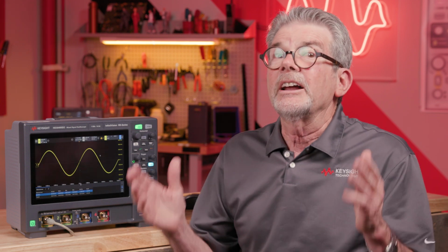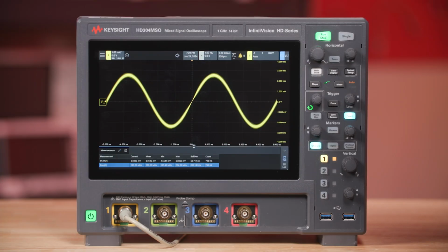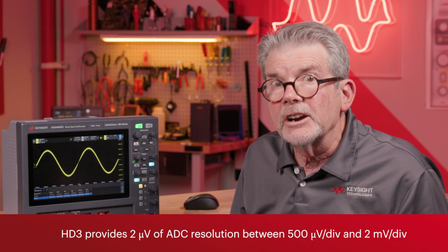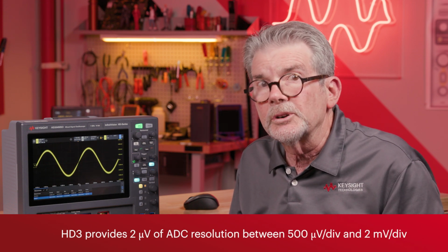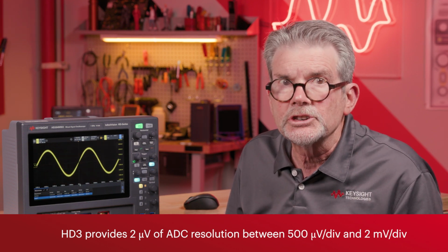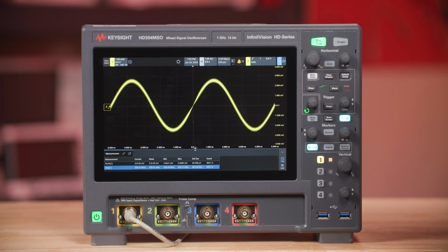Let's now see an example of a fuzzy waveform on a scope that has lots of bits of conversion. This is now a 5 millivolt peak-to-peak 200 megahertz signal with the scope set at 1 millivolt per division. Between 500 microvolts per division and 2 millivolts per division, this scope provides 2 microvolts of ADC resolution. At this low setting, you can probably see some fuzziness to this waveform, but this is the industry best for this class of scope at such a low volts per division setting.